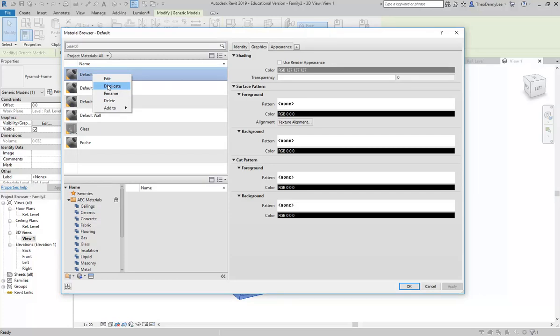But if you're going to make one for a library that other people... Oh, just because you have most of your materials in the project file. So you'll be doubling up. So if you change it inside the family, it doesn't become a job. No, not always. Not if you've already loaded it into the project. But I'm going to be loading it for the first time into the project now, so it's okay to make the material here, and that'll bring it across into the project.